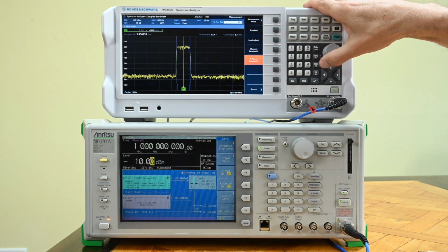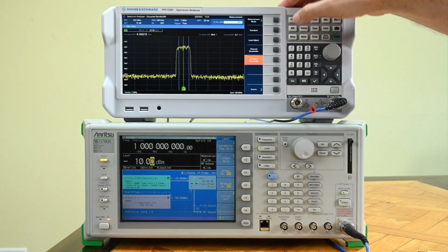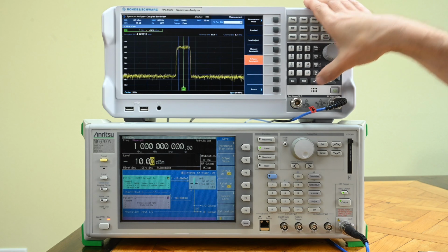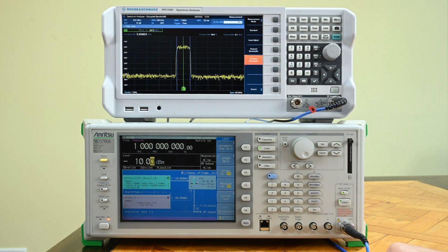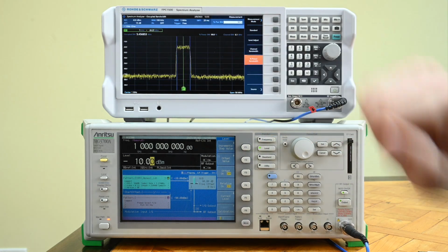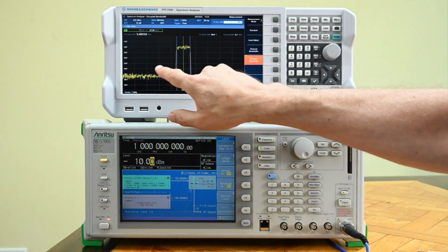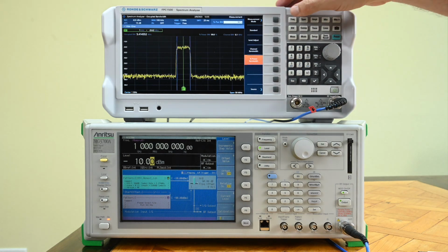If we want to know what is in 80%, yeah, we would see this gets a little bit smaller, the markers here, and the 4.2. I think the 99% is the most used type of measurement for this type of thing. Because you really want to know that very little power is actually going outside the defined spectral plot and goes into the adjacent band, causing interference that we don't want. So yeah, a nice measurement mode that we've got in our spectrum analyzer.